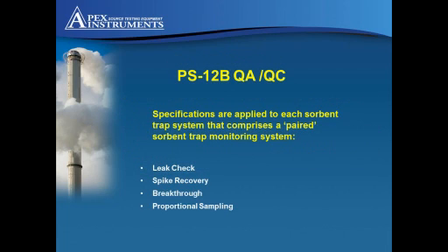So, for each measurement run, the paired traps must pass pre- and post-leak check, breakthrough tolerance, acceptable spike recovery levels, and proportional sampling throughout the test duration.